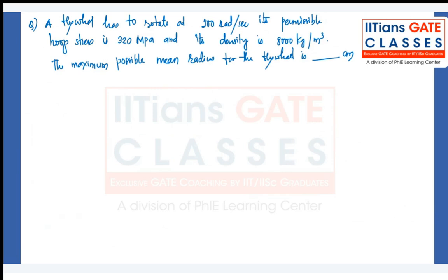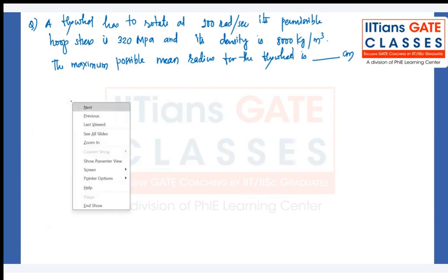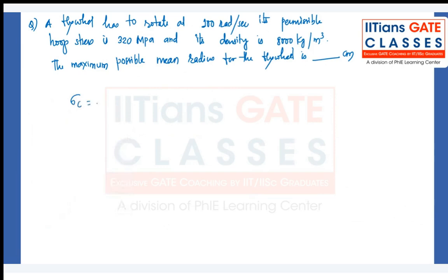So yes, its permissible hoop stress. Sigma c, that is hoop stress. Centrifugal stress is rho v square. Okay, so that is rho r square omega square, we can say. So the value of r is the square root of sigma c by rho omega square.